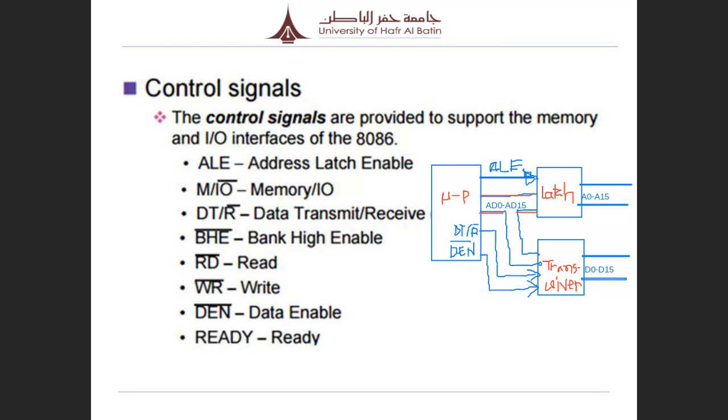So now look here, this is the 16 pins AD0 to AD15. At the beginning, the microprocessor sends the ALE signal. What is ALE? You can see here, Address Latch Enable. That enables these address latches. Latches are like a gate. When it is enabled, it is active, which means it opens the gate. So the microprocessor sends the address information on these 16 pins.